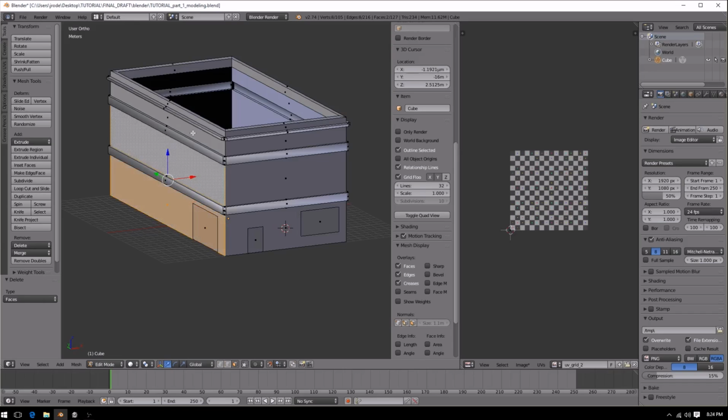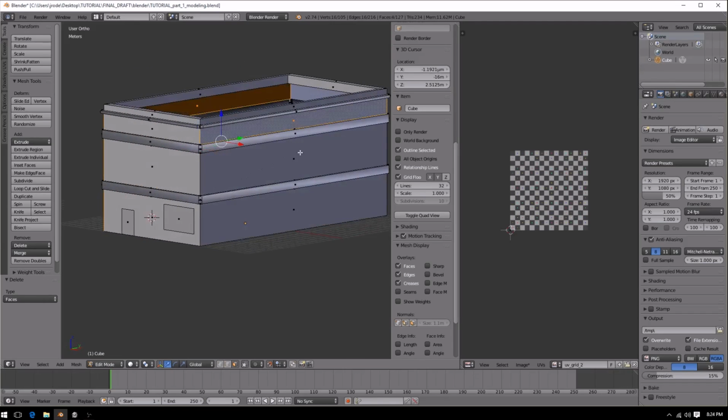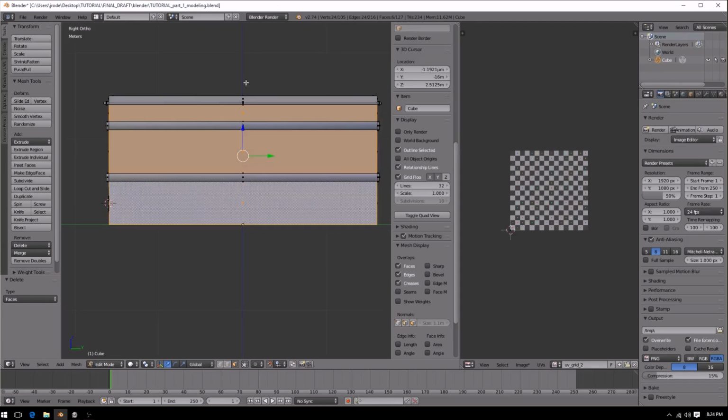So I'm going to select the side walls here, anything I want brick, and again I'm going to go into the side view by hitting 3, and I'm going to go ahead and hit project from view, and now we've got our projection out here. And again I'm going to select A, hit everything, click G, and then Y to just move these straight down. You'll notice they have gaps in them because we didn't actually unwrap these pieces, and we extruded these pieces earlier. So the extrusions don't actually come out until we unwrap these pieces.